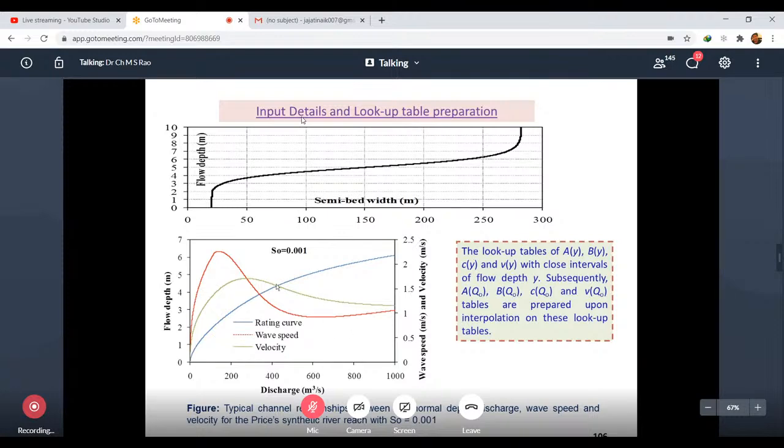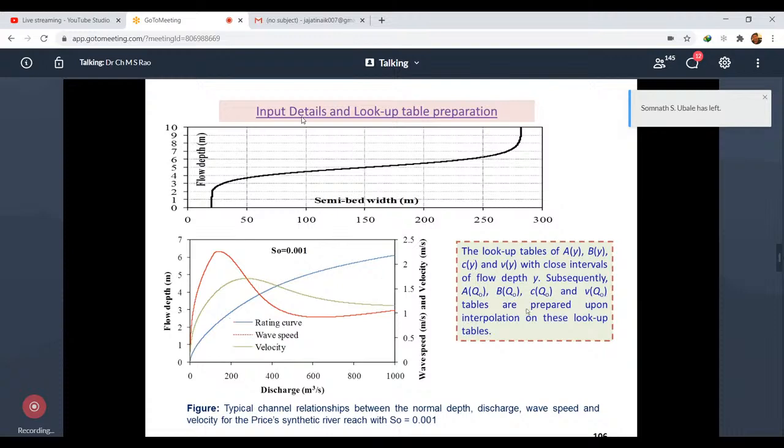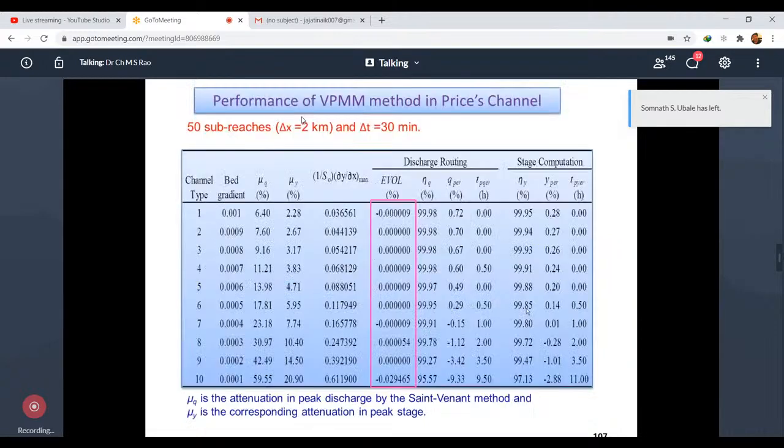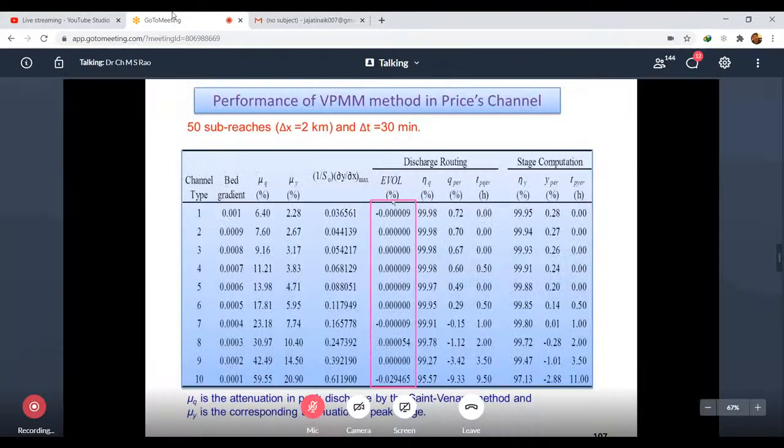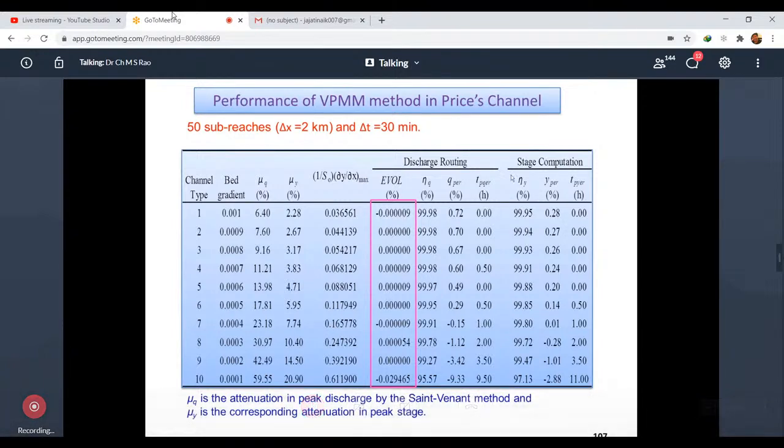Using this gauging station, one can calculate the wave celerity and the flow areas, the wave speeds and wave local velocities, using the normal rating curve. So this lookup table I have calculated and used for different varieties of bed gradients with roughnesses, and again checked the various parameters, and the discharge and corresponding discharge stages also. From the discharge, we have computed the stage.